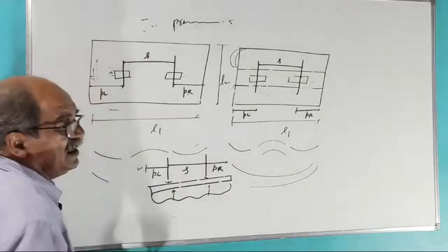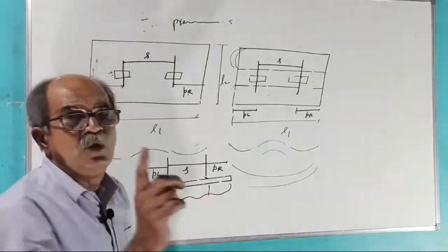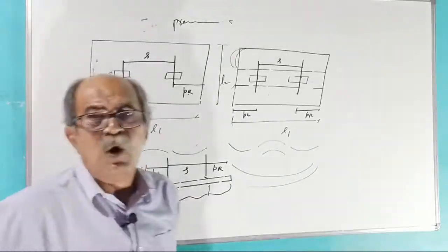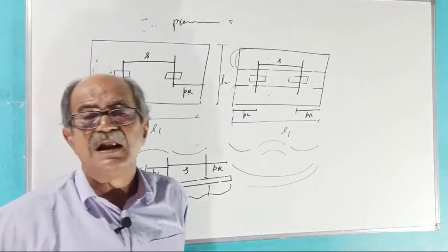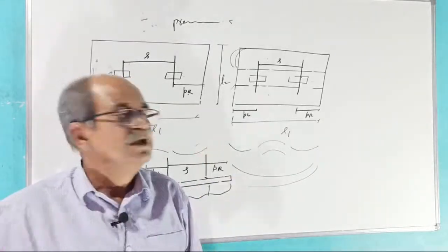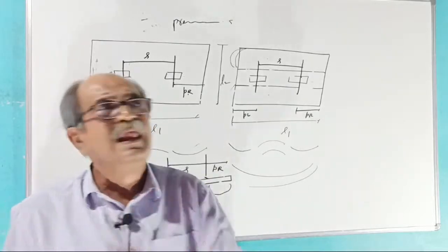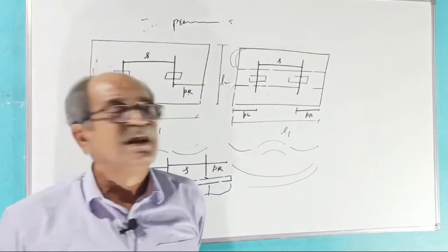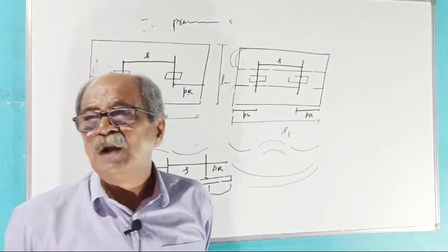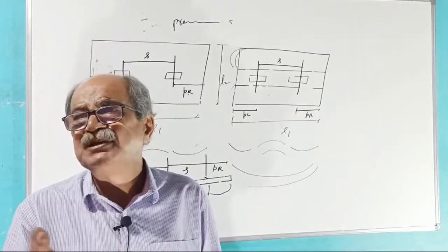Some symbol required for me: PL, PR. Okay, now, do not make PL equal to PR. Be careful. Do not make PL equal to PR. A small Excel sheet you can prepare later if you want. But usually people go by judgment. Many people, by judgment, decide to create the model, run it, and check the pressure. If the pressure comes safe, they proceed further. If the pressure is unsafe or there is a problem, they change the dimension and rerun it. So not a big issue.